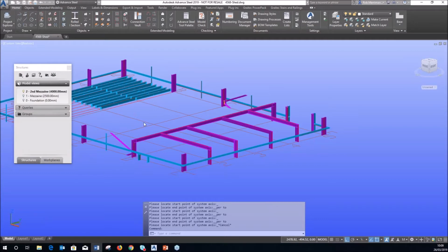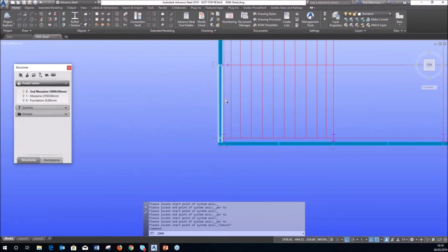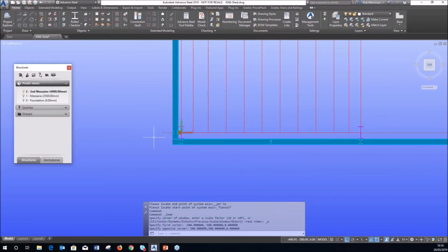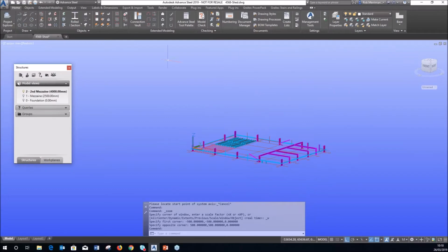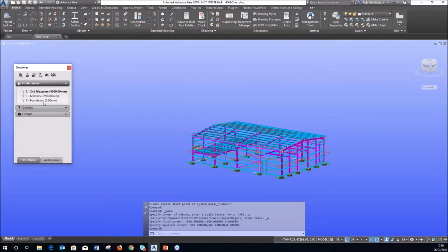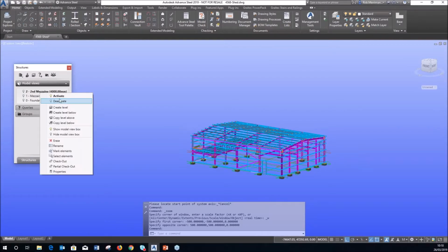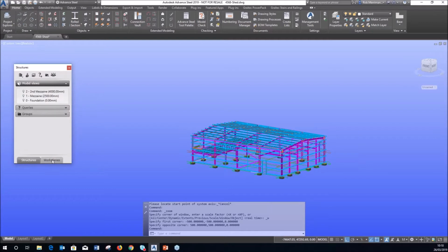You can set them up at the beginning of your project, and then if you're modeling on that level, double click on it to take you to a plan on that level and make sure it's activated, and then everything that you create will be associated to that level. The other clever thing that we can do, so we're going to move on, that's a real rough breakdown of levels. We're going to move on to work planes.